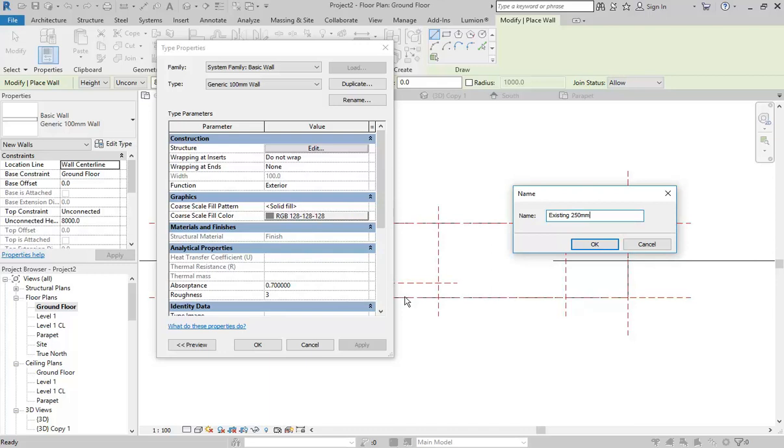Well, that's right, you'd think there would be a cavity. Normally there is, but it would have to be a thicker wall. It would be 270, and that would mean you'd have 110 and then a 50 mil cavity and then 110 again. That's right. Well, in some cases, but in this one, I'd assume because of the age of the building that they actually don't have a cavity.